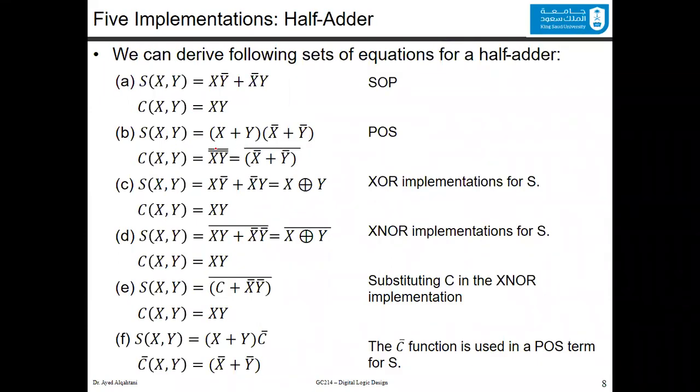You can have multiple half-adder implementations. I listed 6 of them in this slide. We can derive the following set of equations for a half-adder. This is the implementation using sum of products, which is the one that we discussed in the previous slide.